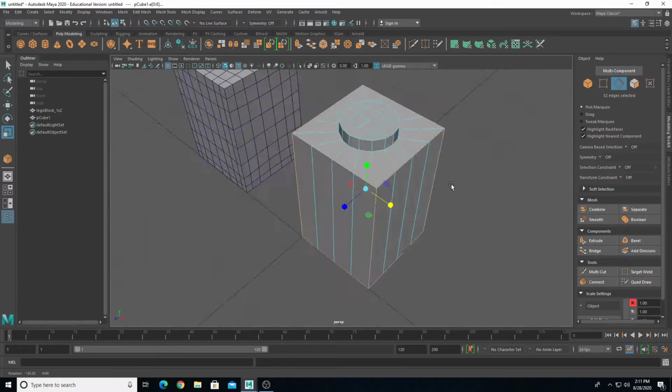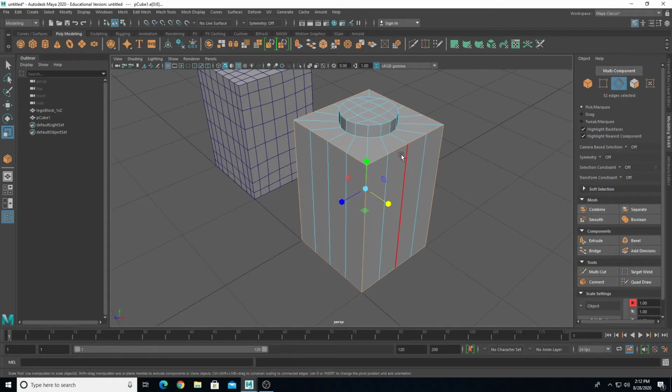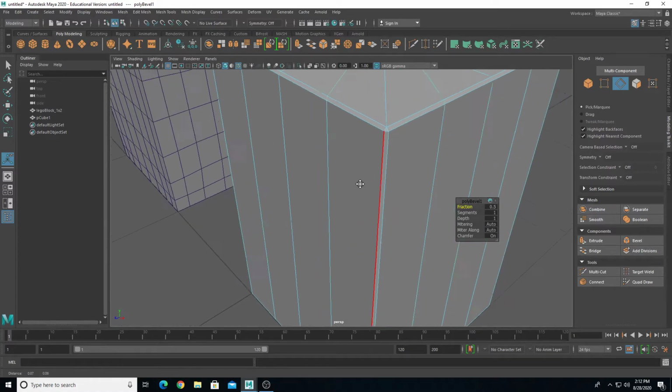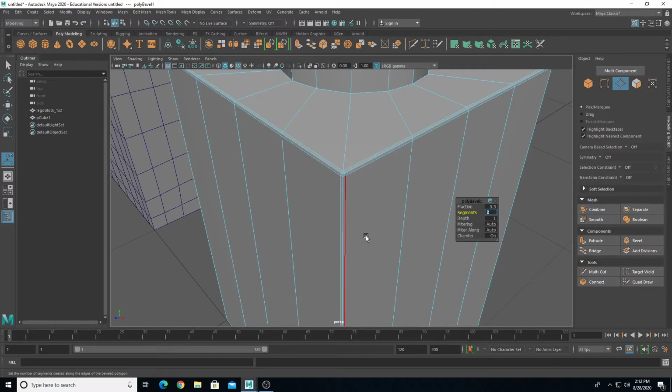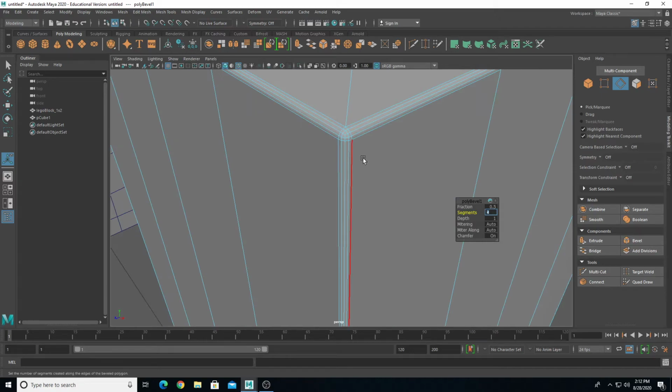And I want to do bevel. So with the bevel tool, that will round off the corner. So if I select all those edge loops, and it's important to make sure you have full edge loops. And if I do bevel, that will bevel that edge all the way around. Now if you leave the segment at 1, then we have a triangular bevel on the corners. But if you change the segment to 2, it will keep everything with 4-sided polygons, increments of 2. So if I do 4, I'll do quads there as well.